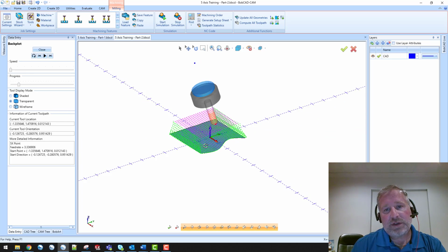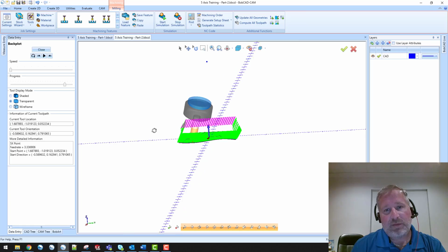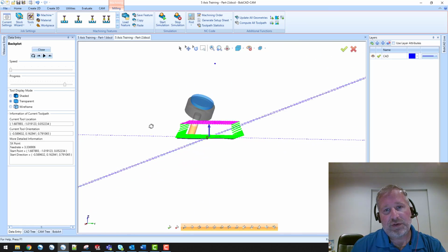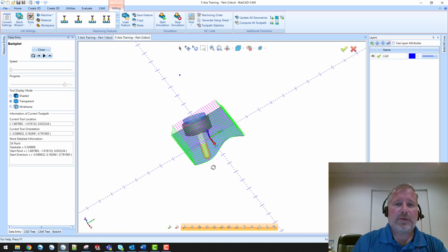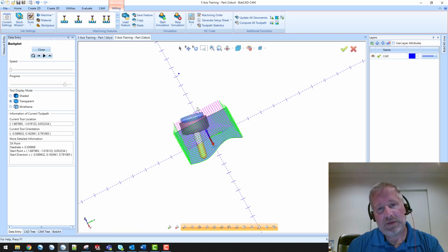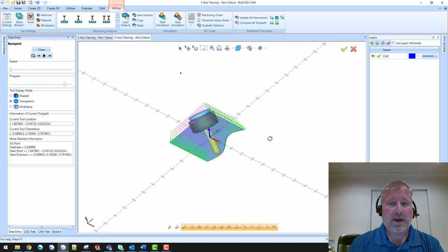So even once we get over to the side where the edge is curved, we will see that that tool is cutting that curve, but even at that position, the tool is always going through that point. So there's a better applied example similar to like port machining that I will be showing next, but I just wanted to show you real quick on a flat surface what that looks like.